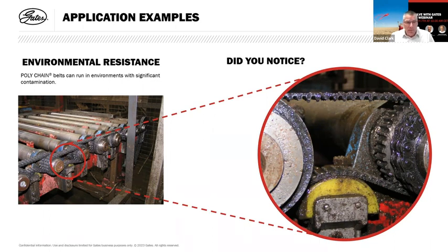The belt drive is being tested to make sure it can meet the requirements of the application. But when it does replace the chain drive, it will eliminate all of this need for lubrication, the dirty oil, the cleaning, the cost of oil, the cost of maintenance, and you can replace it with a clean, low-maintenance belt drive. What it also does is show the capability of the belt drive to run in these types of environments if necessary. But in this case, you can eliminate that.